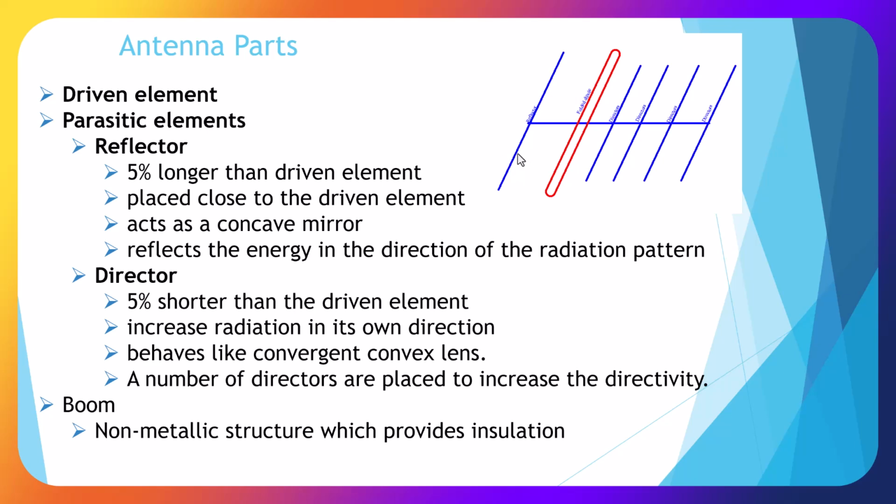And this one back here is a reflector. It's 5% longer than the driven, and it's placed close to the driven, and it acts as a concave mirror, and it reflects energy in the direction of the radiation pattern.